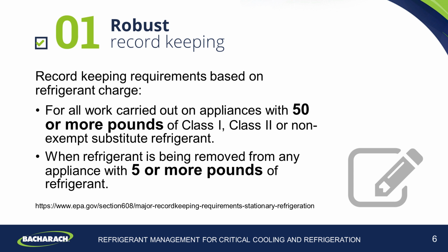A far lower size threshold exists for refrigerant removal. Refrigerant removal records are required whenever refrigerant is removed from any appliance with only 5 or more pounds of refrigerant. All records must be kept for a minimum of 3 years. So, when are the records required?